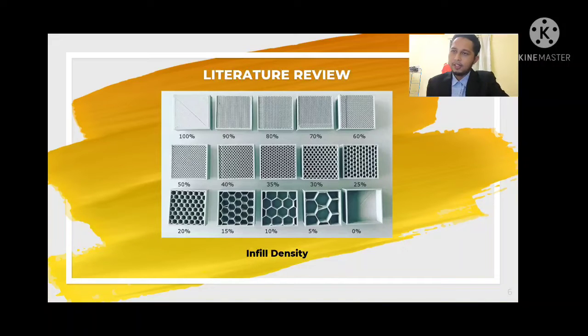What is infill density? The infill density defines the amount of plastic used on the inside of the print. A higher infill density means that there is more plastic on the inside of your print, leading to a stronger object. An infill density of around 20% is used for models with visual purposes. Higher densities can be used for end-use parts.